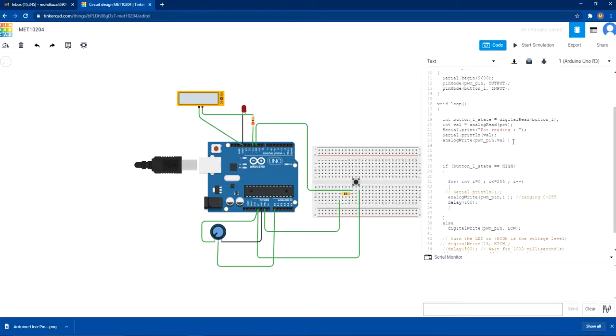But you need to remember that for the analogWrite function, the maximum amount will be 255, but our input will be 1022. The maximum will be 1024. To ensure that the resolution is matched between the analogWrite function and the analogRead function, we need to divide the value that we supply to analogWrite by 4. This means that the maximum value will be 255.